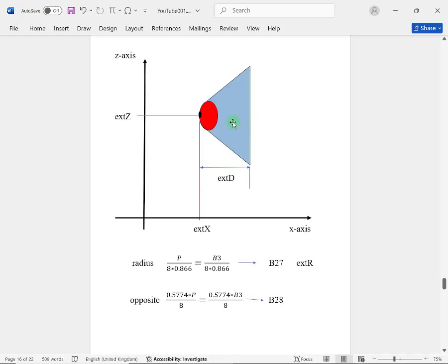Here we have the nut cutter. Now, I don't insert the full circle. I use 2 arcs and join at that central point there. My reasoning there is it gives a unique point to traverse the helix.